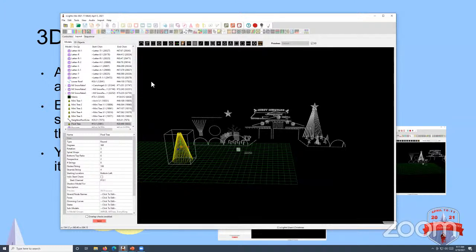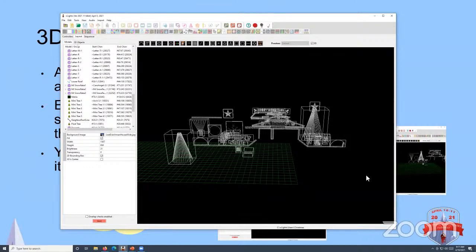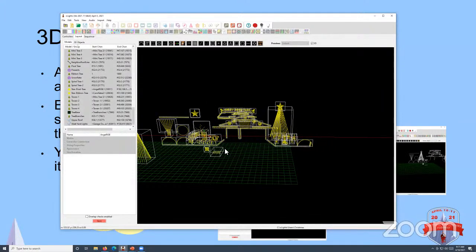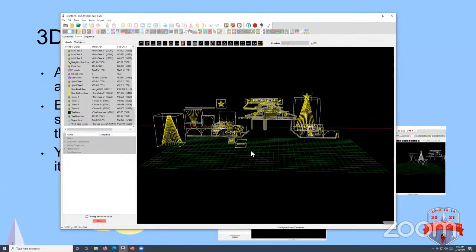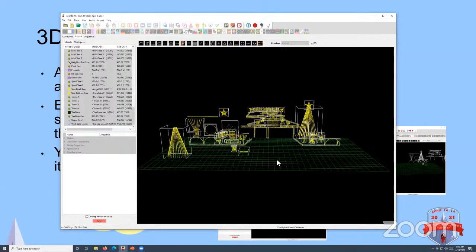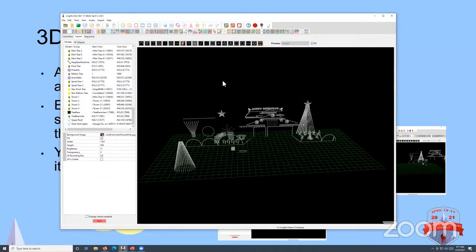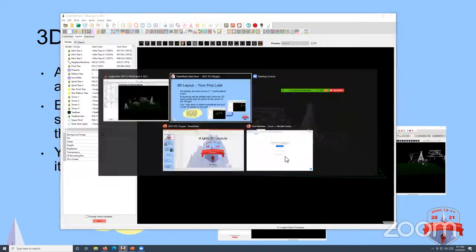So if you hold down Shift and start dragging, I can highlight that whole display. And then there'll be a little handle there where the axis is. I can grab that red handle and I can move all my models over. So if I wanted to quickly get those models centered on that grid, I could do that. And to deselect, I'm double clicking in empty space. That's something I'll go over later as well.